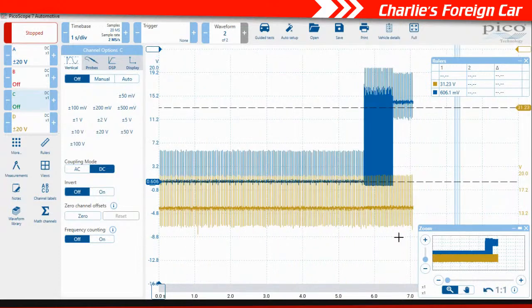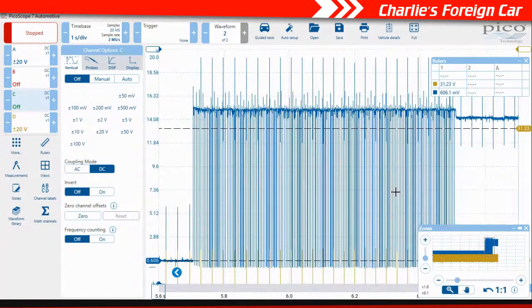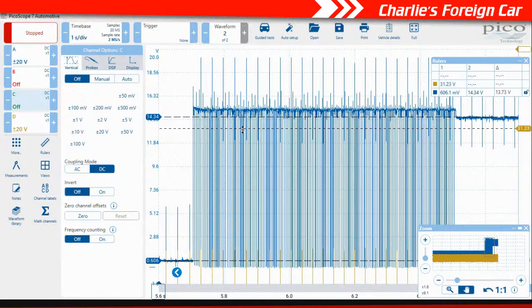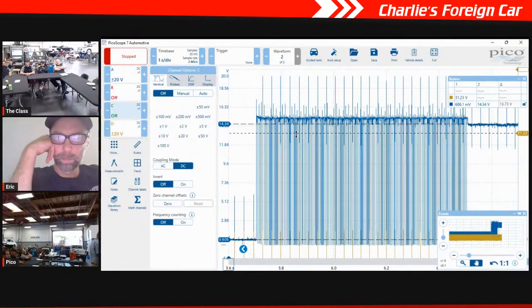And then it went right back up to this pattern when we let off, which is essentially back off. So that's like zero activation. So it's got a little pulsing going on there, maybe 90% off. Okay, so go back into live data so we can ground the blue line. We can take this blue line and then just ground it with the power probe, yeah?